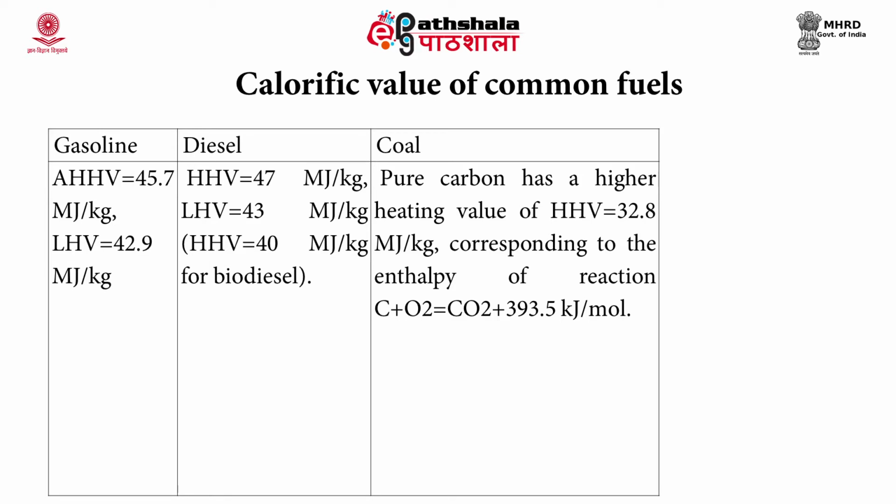With respect to the enthalpy, you can see that C plus O2 produces CO2 plus 393.5 kilojoule per mole. So, here the actual coal has a heating value which is made up of the contribution from the carbon, hydrogen and sulphur oxidation, assuming that these bonds are free, minus the contribution of existing bonds, particularly those with oxygen, which could not be further oxidized. So, here the oxygen content reduces the heating value for complete combustion, since it is already bonded to hydrogen and carbon atoms.